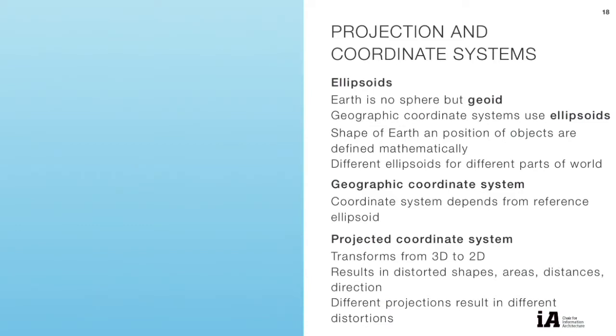It really comes down to this projection technology. Therefore, you have to select a coordinate system that fits your location and is right for the reference ellipsoid in that place. Usually, if you go to the agencies and authorities, they will tell you the actual standard for the different parameters. There are a lot of parameters. If you cannot do that, you might leave out the coordinate system, but then you have problems with later queries. So this should be regarded.